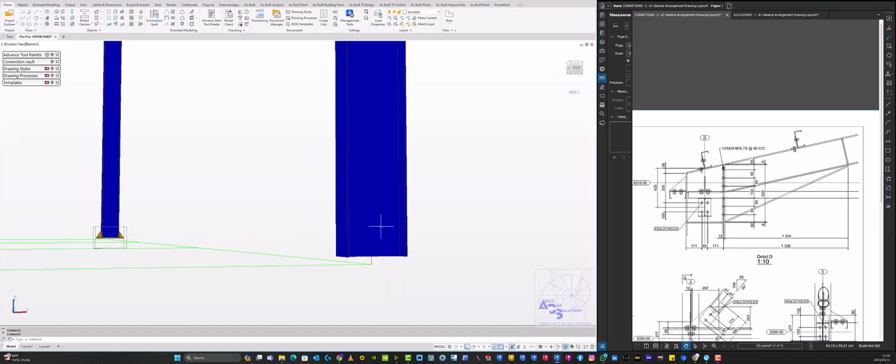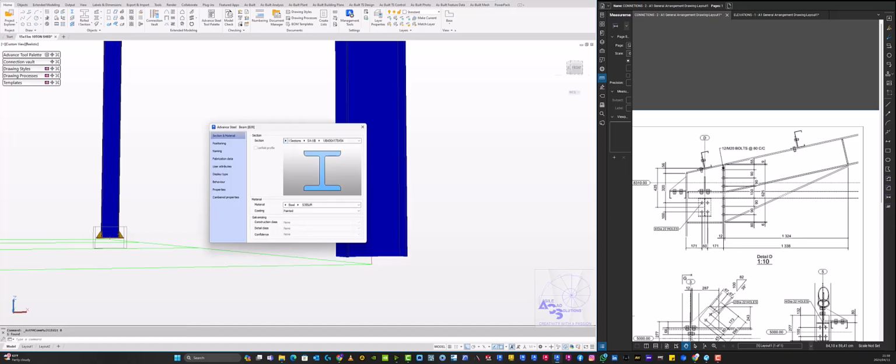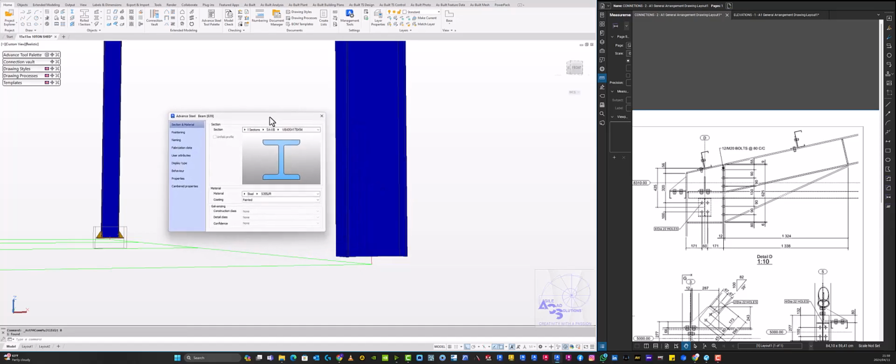So what we do then is we double click on our column so that we can have this tab. Then we go to display type. And the display type, we did mention this. This is where now you can see how we can manipulate it. We go to exact with edge features.